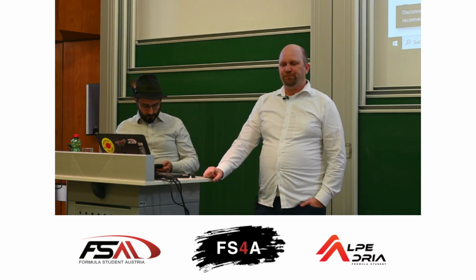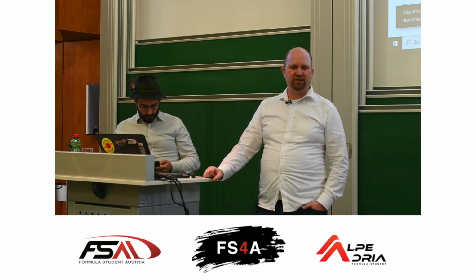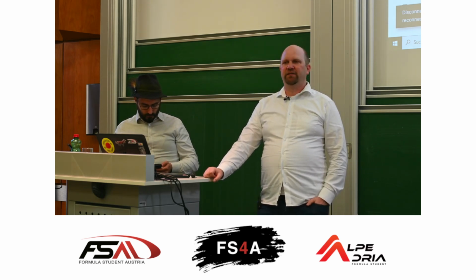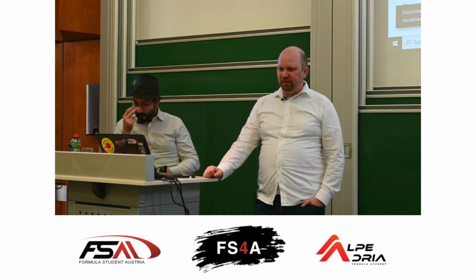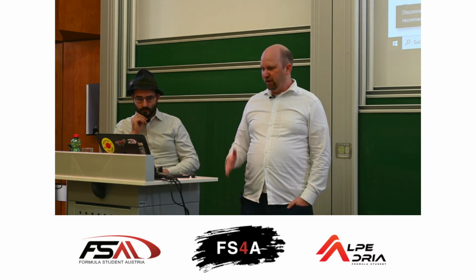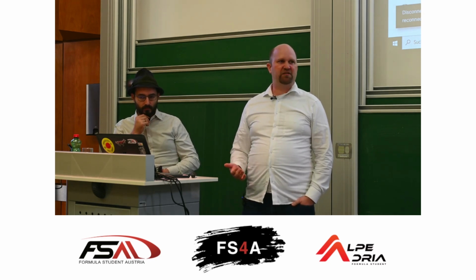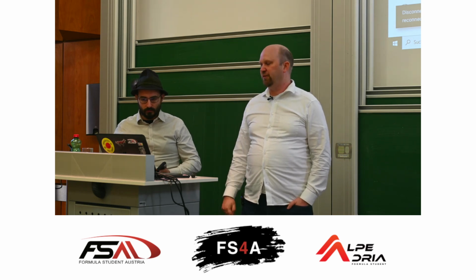So it's the same as in the car. If you press the shutdown button and release it, until now it was allowed that the charger would start immediately. Now you have to have a dedicated start button. So when the shutdown button is closed, everything is closed, then you can press this start button and it will start up.